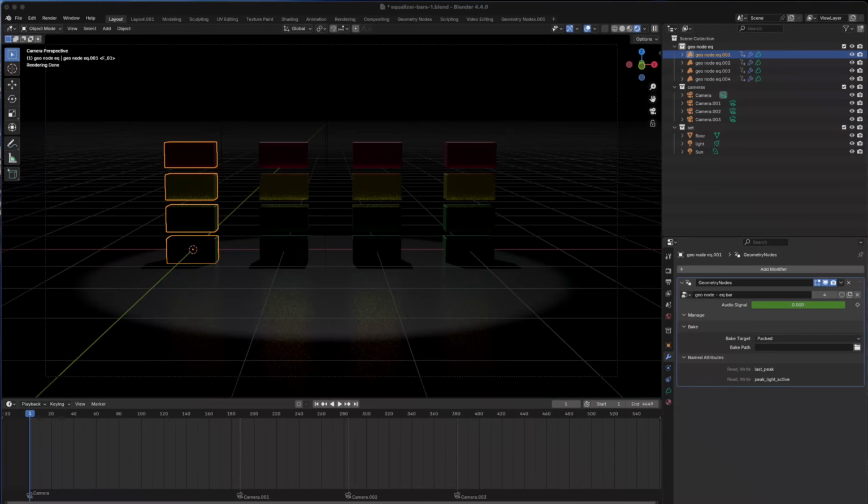So to think about how we switch this, let's take a look again at this view right here, paying attention to the audio signal value that I have here in the corner. So right now, all of the LEDs are off because our audio signal is at 0 even. But then once I add any signal to it, even 0.001, that very first one turns on. And then once we get over 0.25, then we get another one.